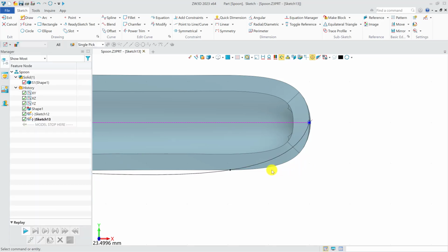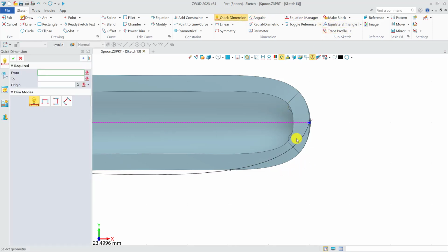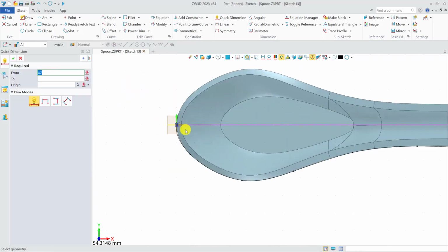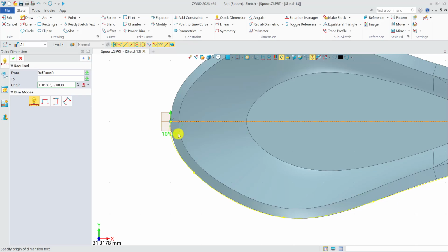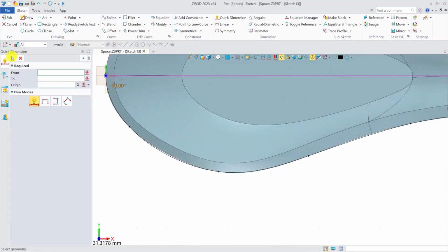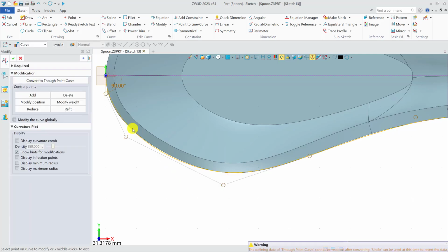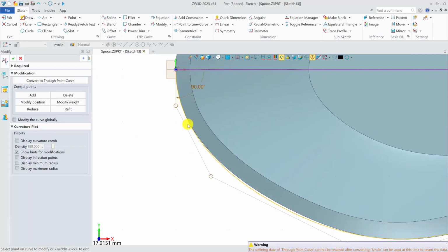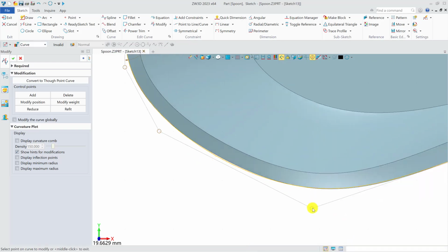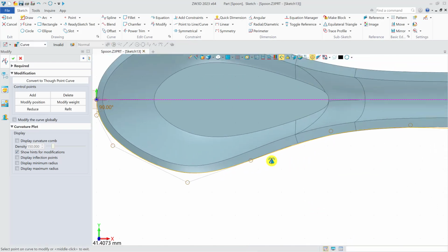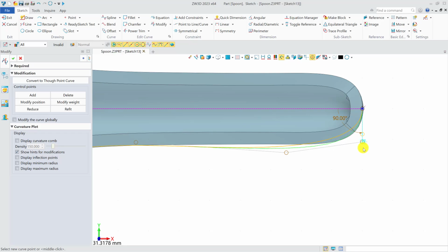And the other key point is that we need to set the 90 degrees on the start and end points. If not, there will be an obvious line in the mirror junction. Because we need to mirror the shape in the end. It will affect the appearance quality. After setting the 90 degrees, we adjust the points. We need more patience to adjust it.